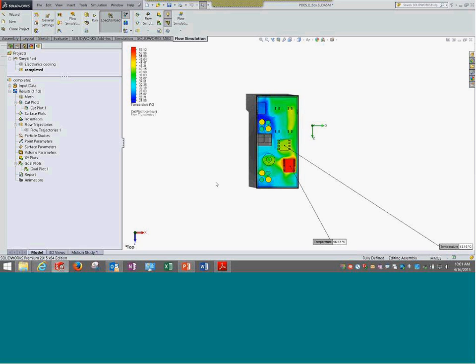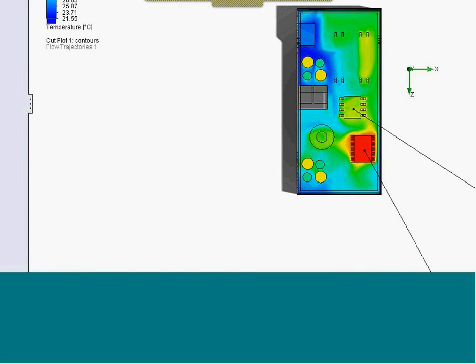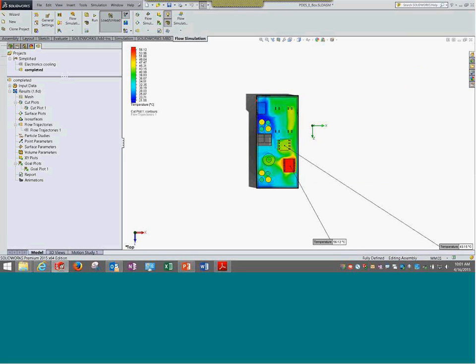One more thought which came while seeing this. I could also do something by which the air is not going out and is deflected in this direction. It comes here, and there is a kind of recirculation which happens and takes the air out from here. So probably change the design such that it goes in that way. There can be many different thoughts, but this tells you how you can understand, manipulate and play with the scenarios.